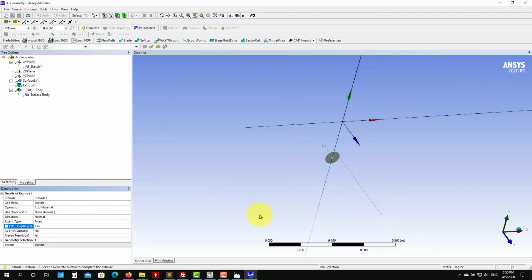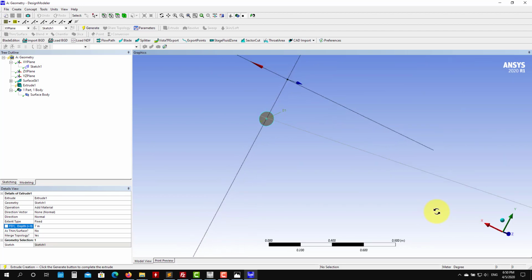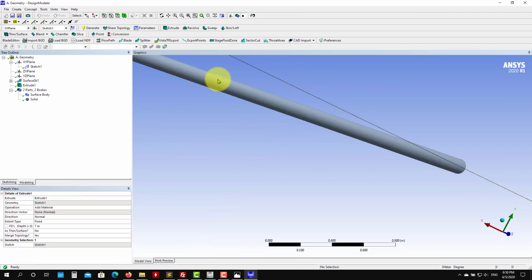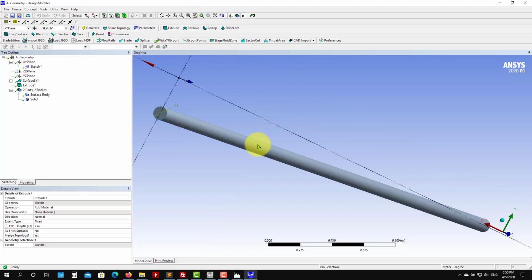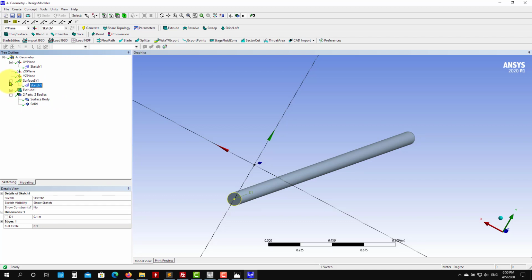So as you zoom out, see that you have here a reference of how we will do it, okay? So here you have different options. You can play with them. So you press now generate, and voila, you have your geometry. Okay. And here, see in parts, you have everything. By the way, everything is parametric. So if you double click here, you can modify. Also, you double click, you can modify this one. Okay, fully parametric. So here you see that we have our solid and the surface.